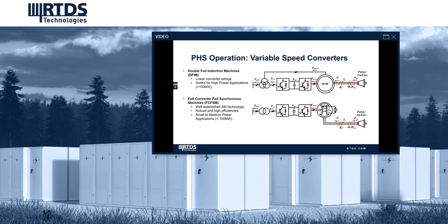The downside is that there is a longer transition period between pumping and generation modes, since the turbine blades have to fully come to a stop and change direction to switch operation modes. Variable speed units with power electronic converters provide increased reliability and flexibility by providing fast power and frequency regulation in both pumping and generation mode.